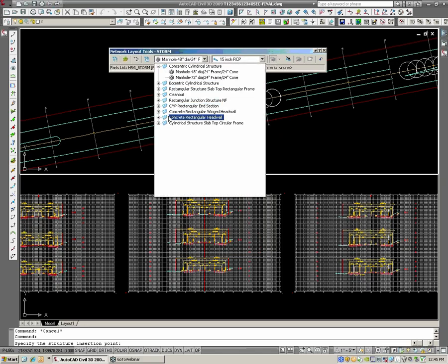And so somebody would have drawn this out previously in Civil 3D for you. In another drawing, you'd have to data reference the pipe network into your drawing. Okay, so you data reference this pipe network into the cross-section drawing.